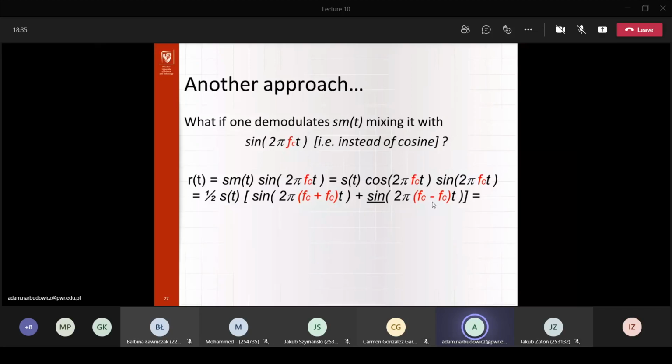So you are in a way right that what we get is wrong. To be more precise, if we use the cosine for modulation and sine for demodulation, we will get pretty much nothing, or at least nothing at the baseband that we are looking for.